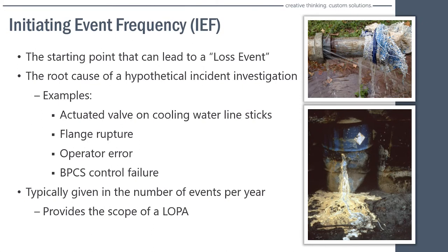And for example, even in our little simple scenario, we talked about the operator opening and closing the valve. If the operator fails, in that case, they open the valve, but they fail to close it, and the tank continues to fill, that would result in an overfilled tank. That's an operator error. That's the initiating event frequency. And the question becomes, what is that frequency?